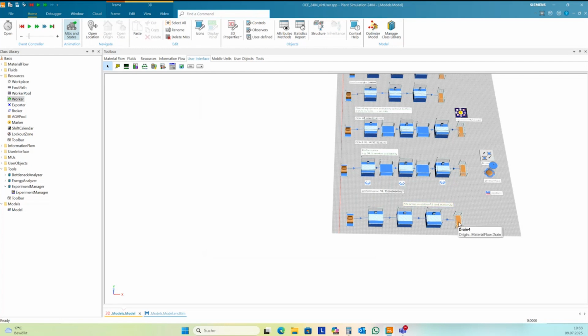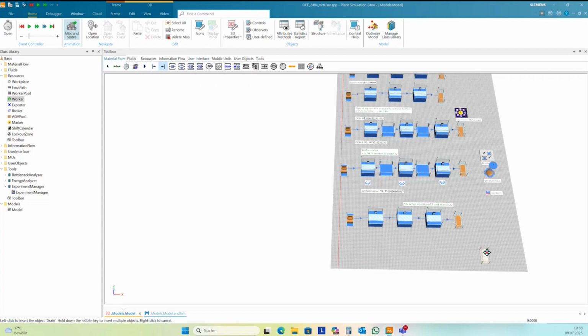Okay, very important is that you add a new train here for this, because you need to separate the scrap and the NOK parts from the OK parts, so that you can count the parts here in the last train. And so I need one more train. And a material flow to this train as a second successor.